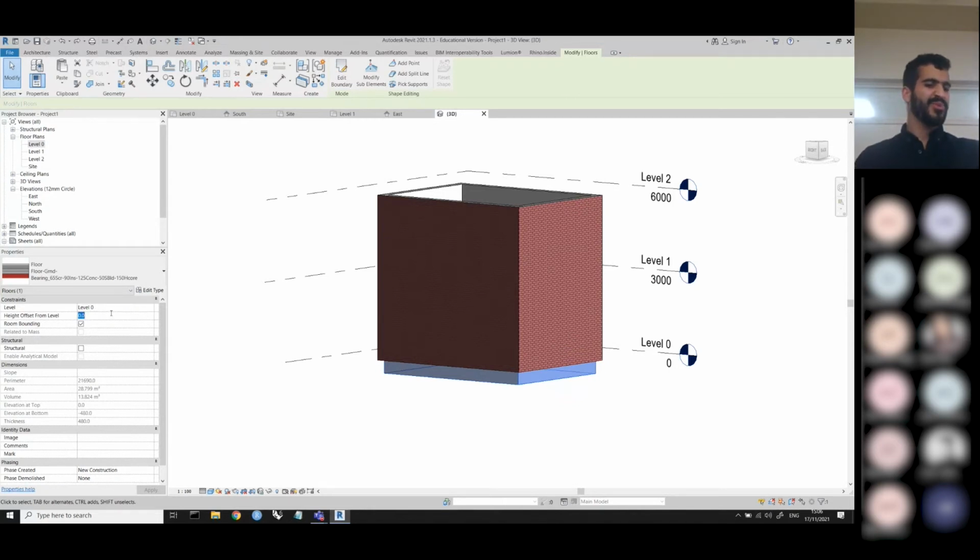You shouldn't really do this unless necessary. You might want to offset. You might want to constrain, but always leave a gap. So here, let's say I want the wall to be constrained 100 mil below my top level. Does that make sense? So I just enter 100 over here. Apply. You can see it's just gone up slightly.